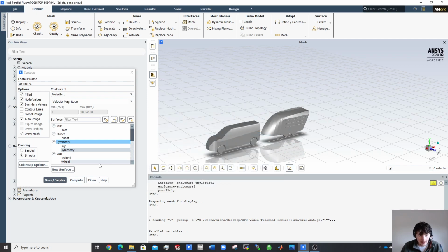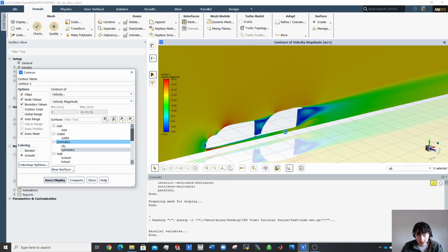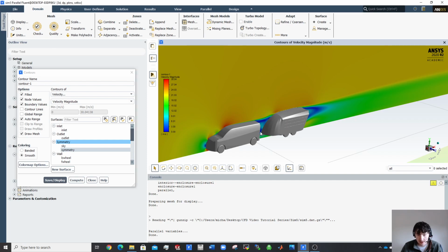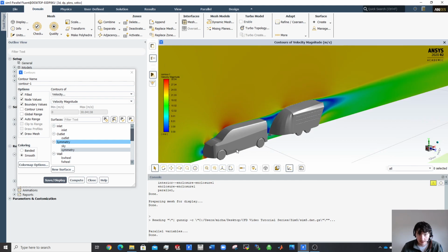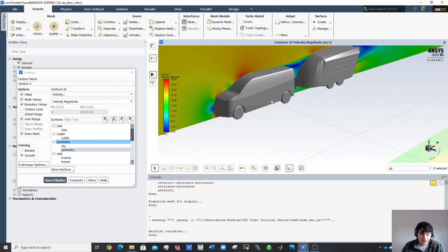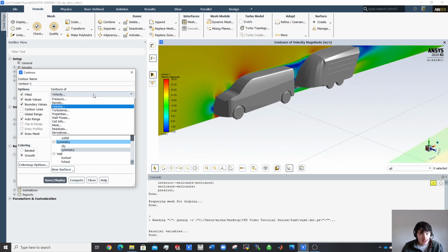Yeah. And then I'll display this pressure thing again, and then I'll have the mesh here. That's if you're interested in how to do that. I could also have a pressure contour plot on that as well. That's another interesting type. So definitely plotting along that symmetry plane, you pick up a lot of information.